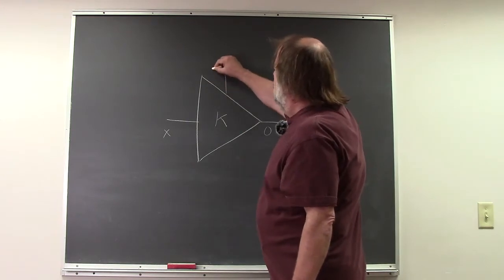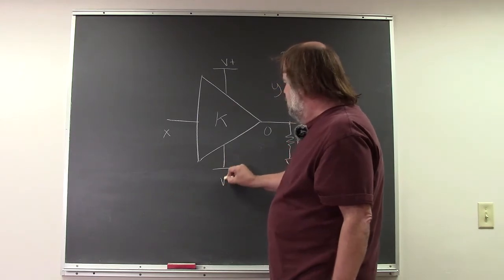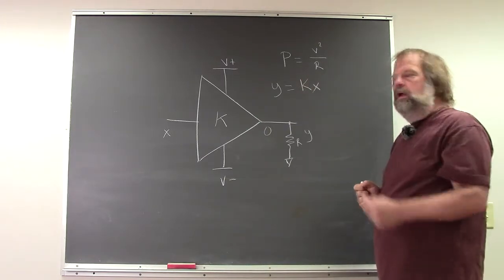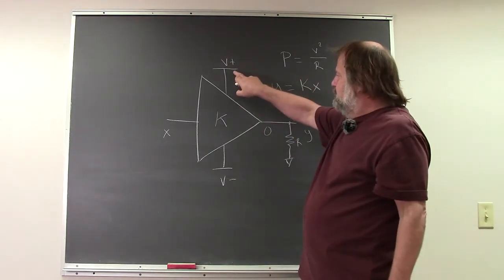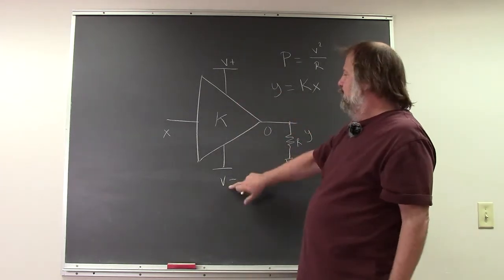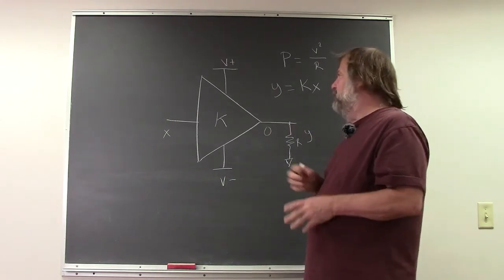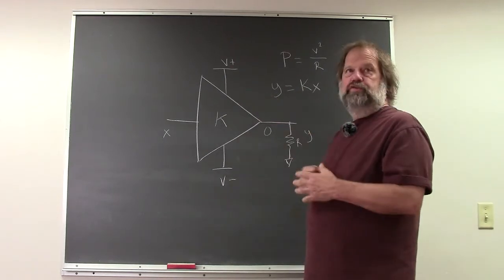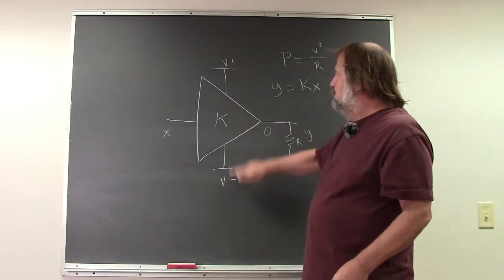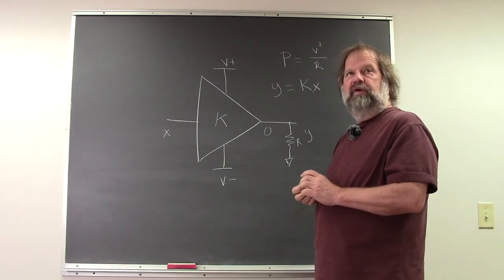If we're talking about most amplifiers, we have a power supply. I'm going to represent this as a power supply of V. These are my supply rails. The amplifier will swing somewhat, just a little bit less typically than that rail and that rail, somewhere in between. But for our ideal amplifier, we'll assume it goes to those extremes. In a vacuum tube amplifier, you might have a little different relationship because you probably have a step-down transformer. And you could also have situations where these are not equal, but we'll just assume they're equal for our discussion. This would still be true of virtually all solid-state amplifiers.